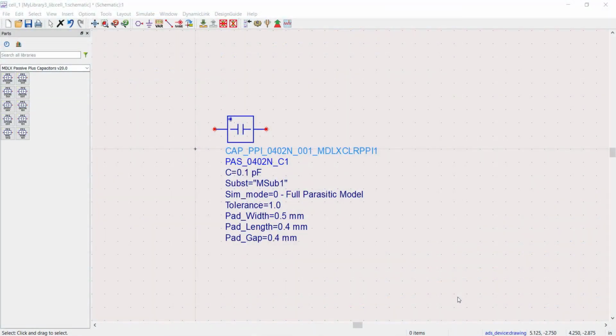Solder pad scalability is one of the main features of Modelithics microwave global models for surface mount capacitors, inductors, and resistors. Since these models scale with respect to solder pads, designers can quickly and accurately determine performance over a range of PCB solder pad stack conditions.